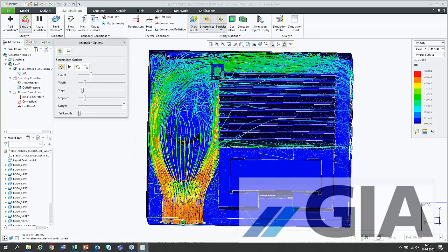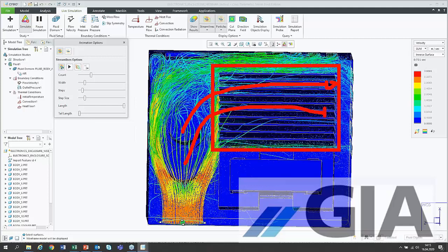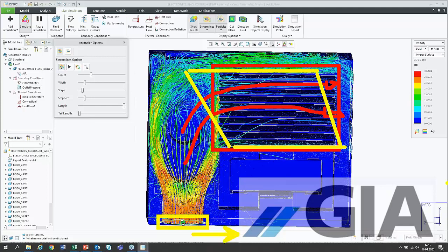And I can see here, yes, my cooling body doesn't work really perfectly because there is nearly no flow through the ribs. Therefore, as an engineer, I think it might be better if I change the extrusion of that body, and in the end I want to have maybe a body with a shape like that one here. And I'd like to move the inlet a little bit to the right. This is just a stupid idea